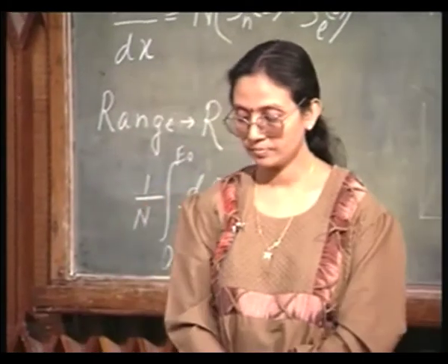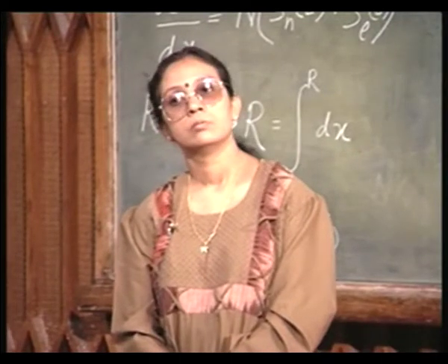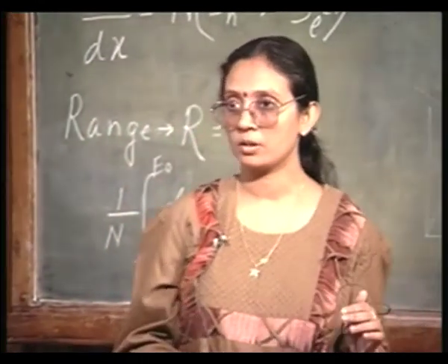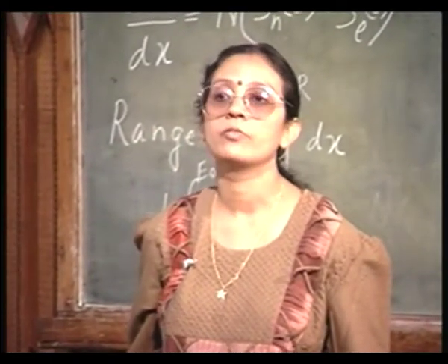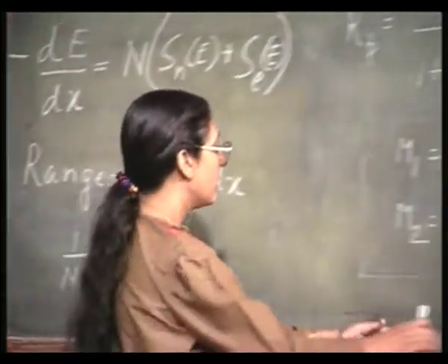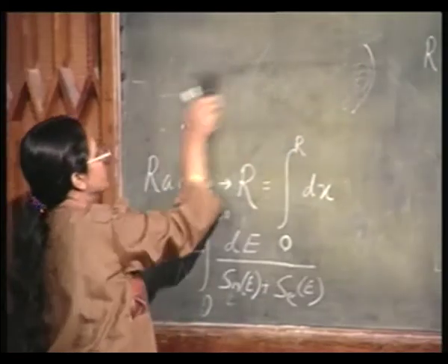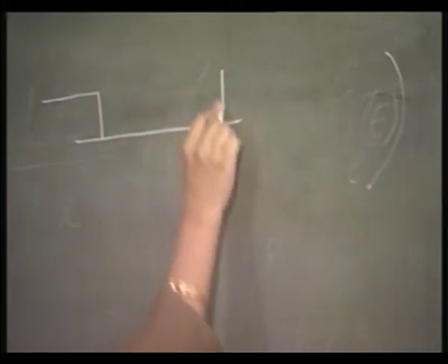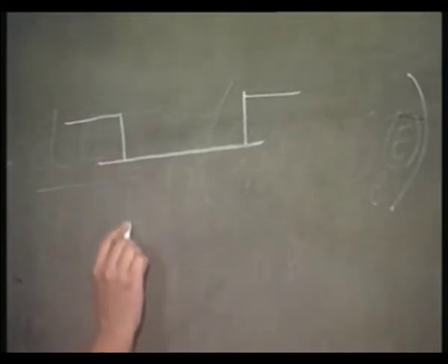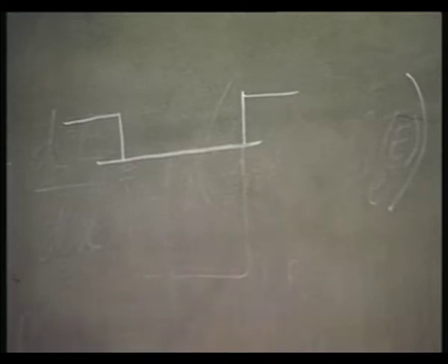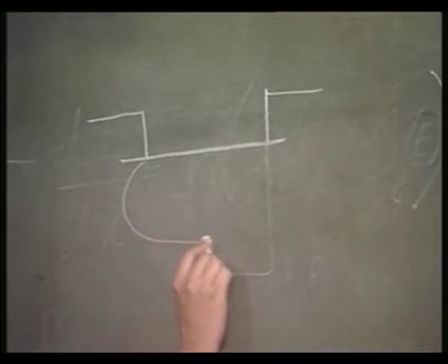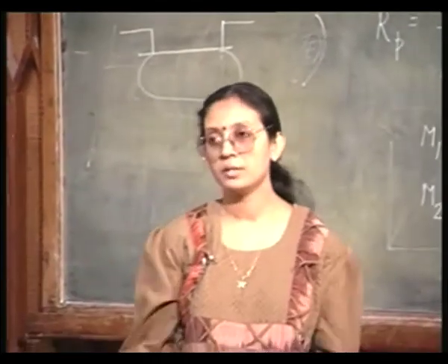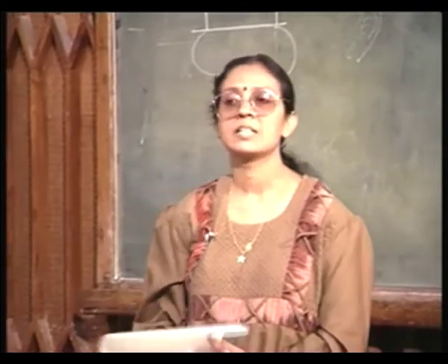So, this is about ion implantation and how the incident beam is moving inside the semiconductor. But again, just as in case of diffusion, you know that if I have a window like this, ideally speaking, I would expect the dopants only to move like this, but as a matter of fact, there will always be a lateral spread, a lateral diffusion. You have seen in case of ion implantation also, there will be some lateral doping, and that is extremely difficult to model.